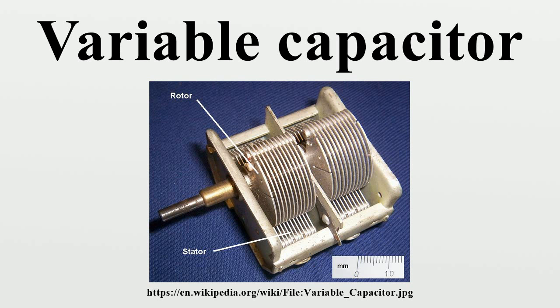Split stator. The closely related split stator variable capacitor does not have the limitation of 90 degrees angle since it uses two separate packs of rotor electrodes arranged axially behind one another. Unlike in a capacitor with several sections, the rotor plates in a split stator capacitor are mounted on opposite sides of the rotor axis, while the split stator capacitor benefits from larger electrodes compared to the butterfly capacitor, as well as a rotation angle of up to 180 degrees. The separation of rotor plates incurs some losses since RF current has to pass the rotor axis instead of flowing straight through each rotor vane.